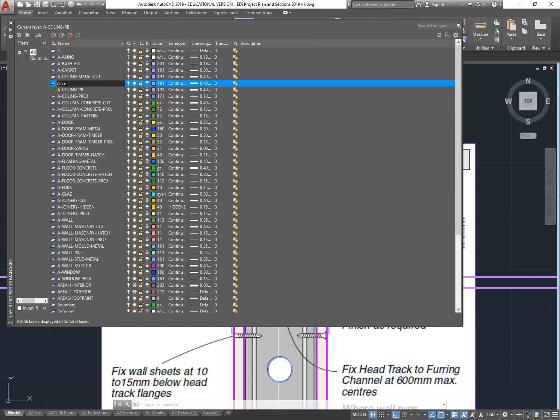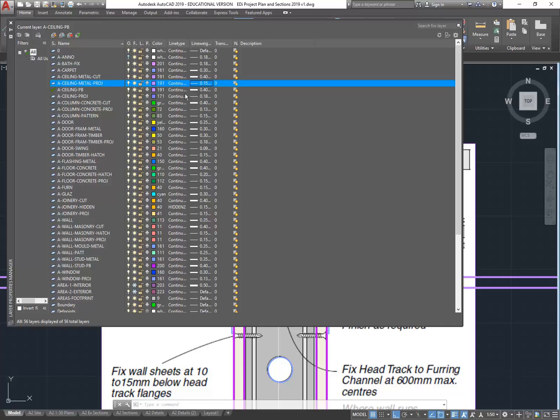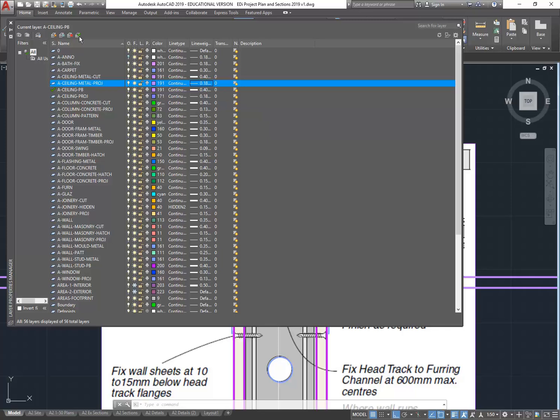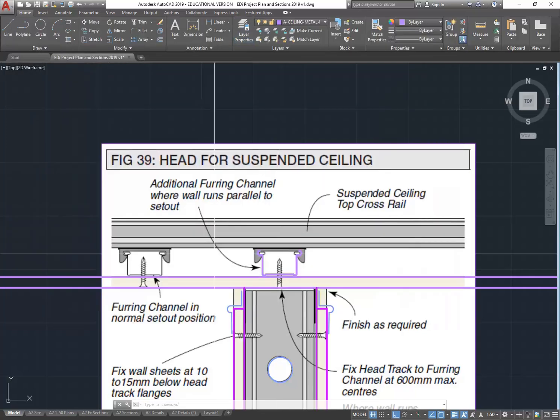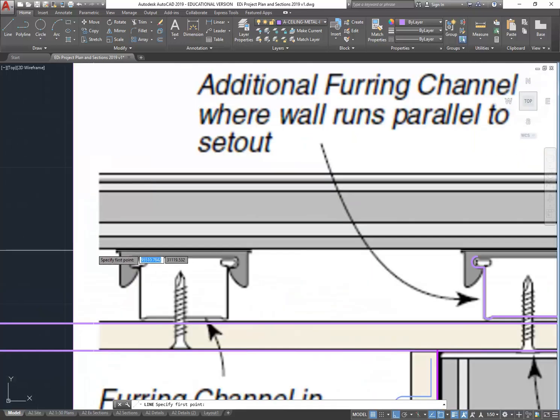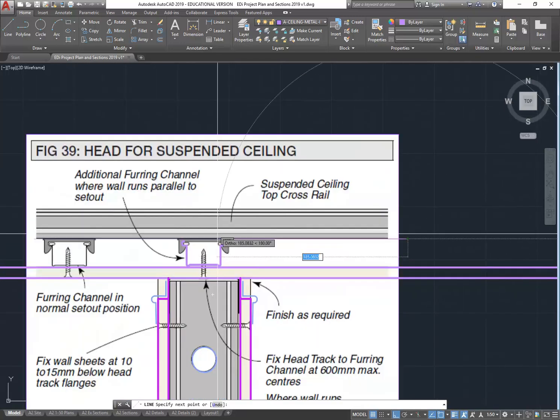So I'm getting fussy, but caps. And then the line weight for this would be much lighter, but not as light as possible because we're in a detail. We can make the lines a bit heavier than normal, but 0.15 maybe is good, or even 0.18. So I'll draw a line coming across there. Don't need to be too precise about this.